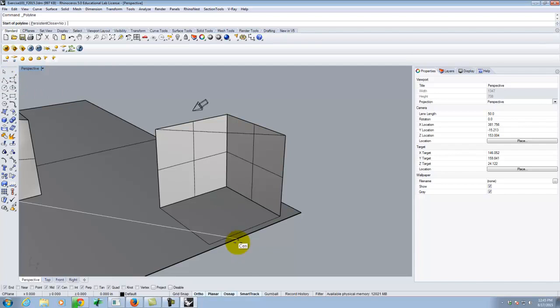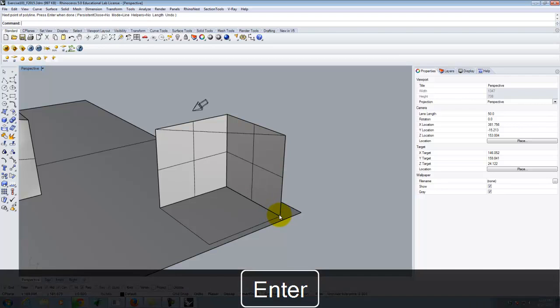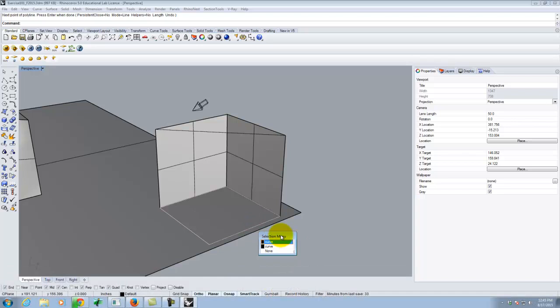Anyway, I'm going to pick the polyline tool, and I'm going to draw a line from here to there. And I'll go ahead and hit Enter when I'm done. Now I'll select this line. Now, this is something that happened to a lot of people that I didn't tell you about. One of the things that Rhino does is very smart when you have multiple objects on top of each other. And right now we don't have that many objects, so it's not too bad to deal with. But it's always helpful because we can choose which object we want. So it brings up this little selection menu because there's objects on top of each other. And we can kind of scroll through, and it'll highlight in this pinkish color which object it is. So we can say, yes, I want the line.